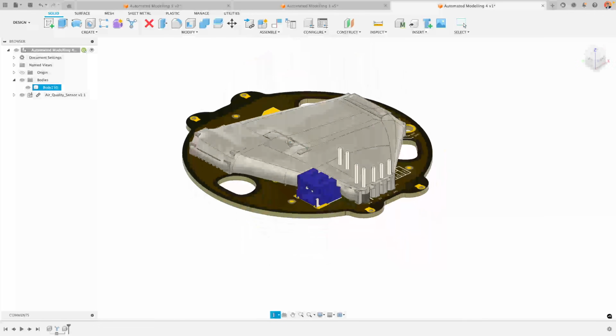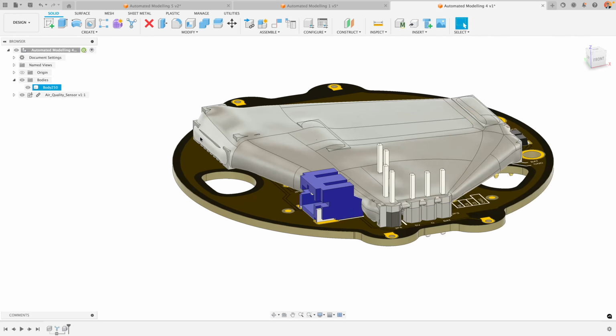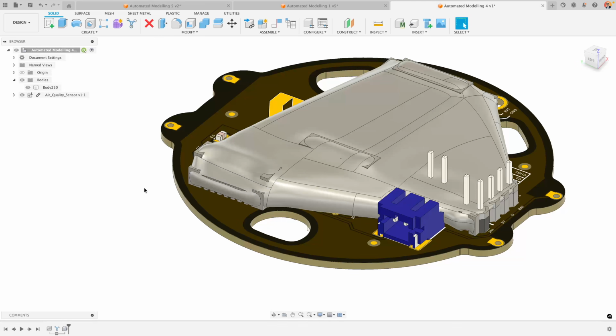Now, of course, that doesn't mean I couldn't edit this. I could go through and I could add parts onto my automated model or model beforehand and include those as faces, such as a snap fit that attaches to the board or something that goes through one of the holes so that I can attach it. Making sure that the part I've automatically modeled is held in place as a single component I've got to hold rather than the 6 or 7 different components on the PCB.